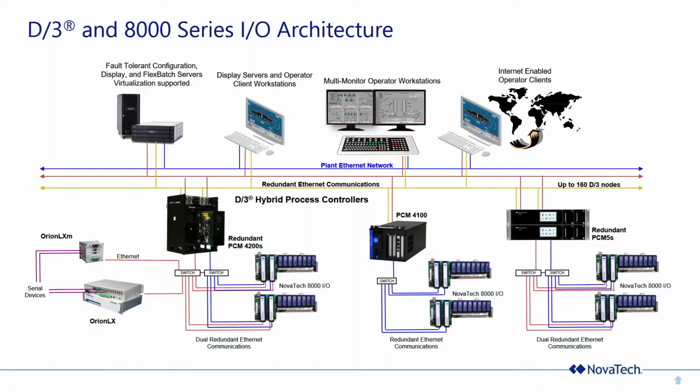Each A and B micro has an EMPC2 card, which has its own switch. Let's just call the switch on the left the A switch and the switch on the right the B switch. So we have A and B I/O networks. The 2 switches are connected together by an interlink so that you can go from PCM A to switch A across the interlink to switch B, and now you're on B's highway.